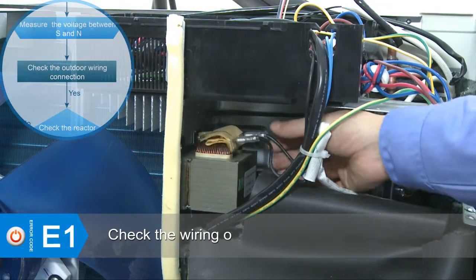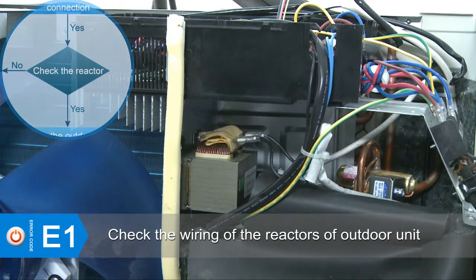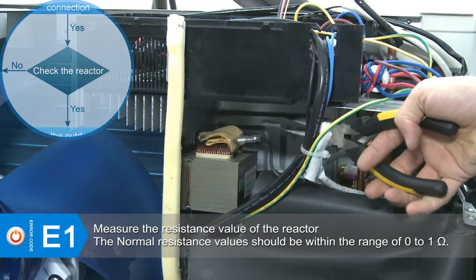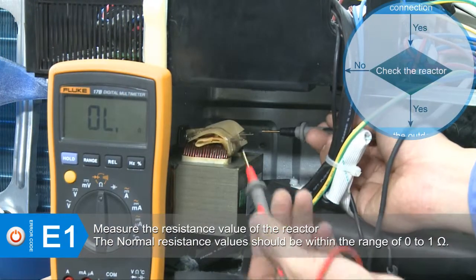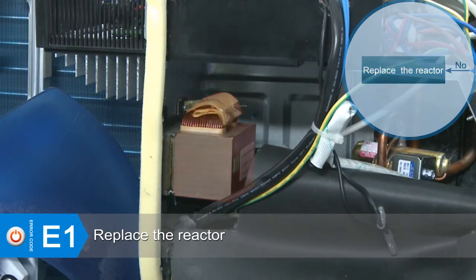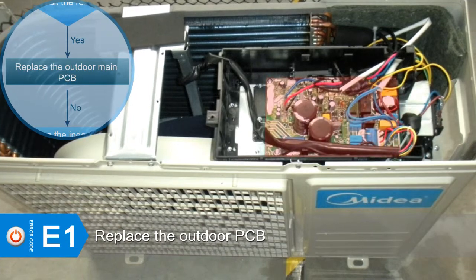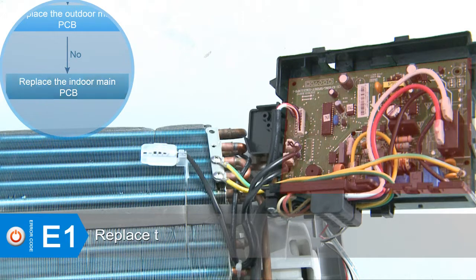Check if the wiring of the electric reactors of the outdoor unit is well connected. Measure the resistance value of the reactor. The normal resistance value should be within the range of 0 to 1 ohm. If not, replace the reactor. If the error still exists after the maintenance procedure above, replace the outdoor PCB. If the error still exists, replace the indoor PCB.